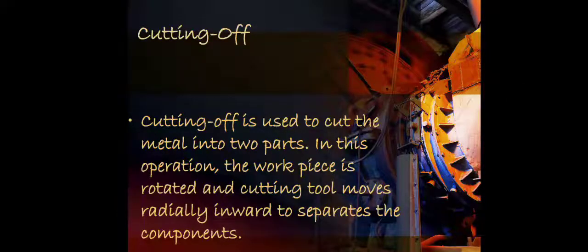Another one is cutting off. Cutting off is used to cut the metal into two parts. In this operation, the workpiece is rotated and the cutting tool moves radially inward to separate the components.